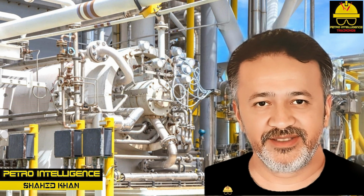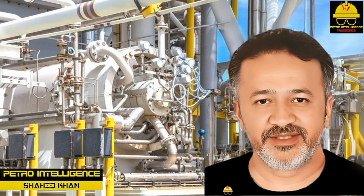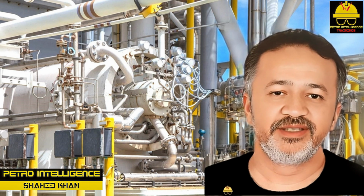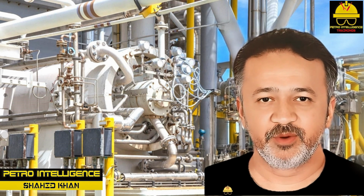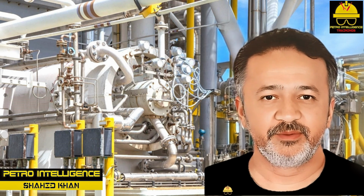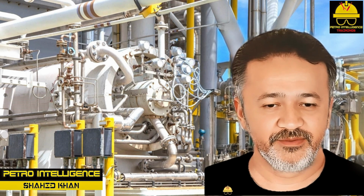Compressors usually can be classified into two groups: positive displacement and dynamic. Positive displacement compressors operate by trapping a specific amount of gas and forcing it into a smaller volume. These designs include rotary screw, sliding vane, lobe, and liquid ring, and reciprocating, piston and cylinder, and diaphragm. The most common type of compressors, reciprocating compressors, work by trapping and compressing specific amounts of gas between a piston and cylinder wall. The back-and-forth motion of a reciprocating compressor pulls gas in on the suction or intake stroke and discharges it on the other.